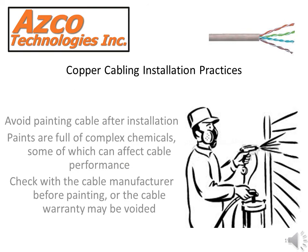Avoid painting cables after installation. Paints are often full of complex chemicals which can affect the cable's performance. Check with the cable manufacturer before painting the cables, or you may void the warranty on those cables. Possibly surface raceways may be a better way to cover up those cables.